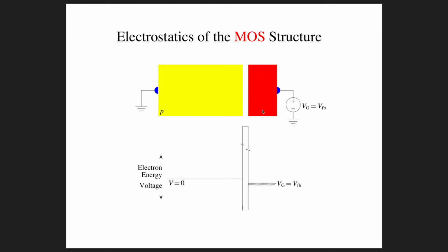The main silicon substrate is a single crystal silicon, and polycrystalline silicon is a deposited silicon that has many tiny grains of silicon crystal with different crystal orientations relative to each other. So it's a less regular structure than the silicon, which is down in the bottom here. But this is doped to a very high level of doping so that it is basically metallic. So this is the M in the MOS structure.